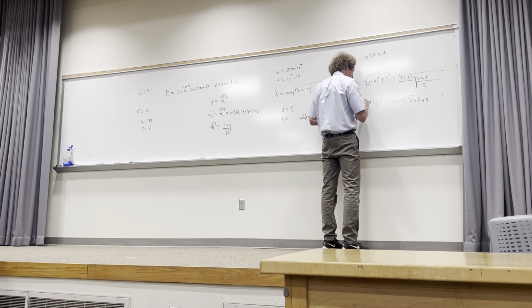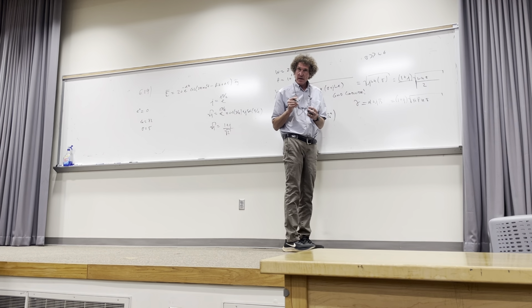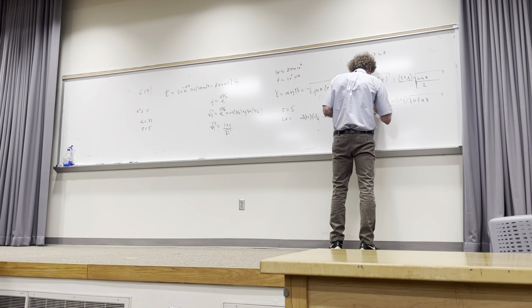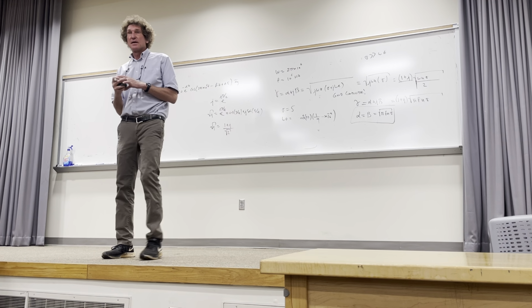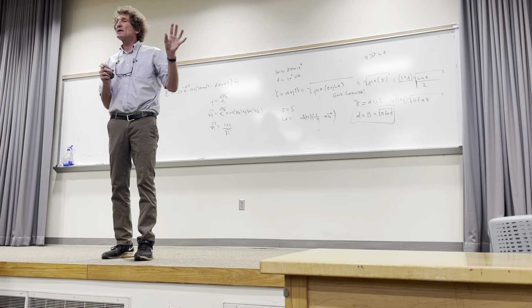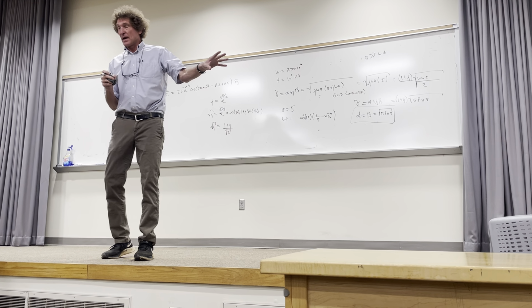I mentioned this before, but this is true for a good conductor. All right, and that means that alpha is equal to beta, and it's equal to the square root of pi f mu sigma. And that's important, because in a good conductor, alpha is equal to beta. Do y'all follow?